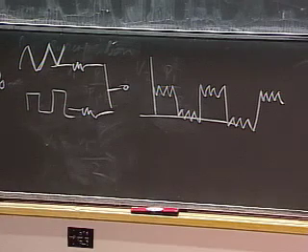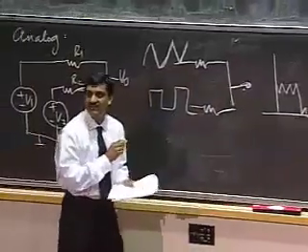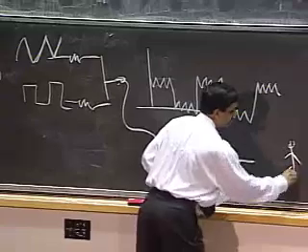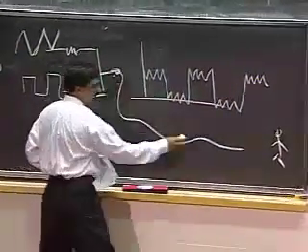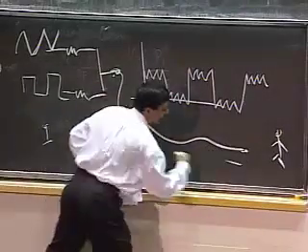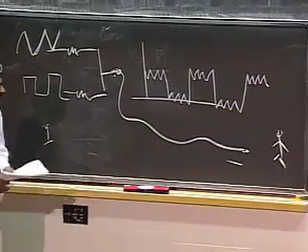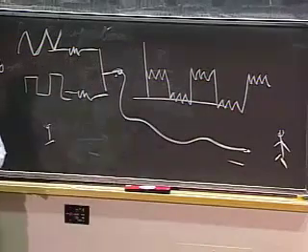Now let me do the following. Oftentimes, I may need to look at this value some distance away. So let's say this person here wants to look at the value. I have this wire, I bring this wire here, and I also bring the ground connection, and I look at this value here. When I have a long wire, I can get noise added onto the circuit.